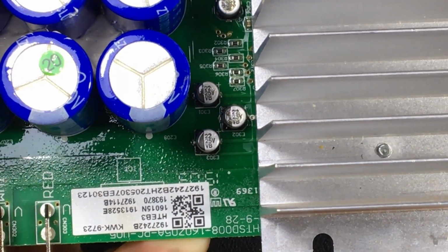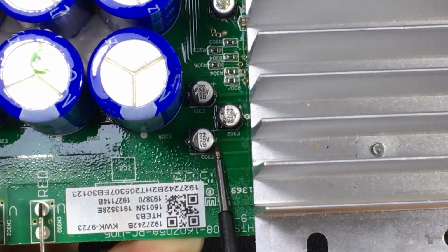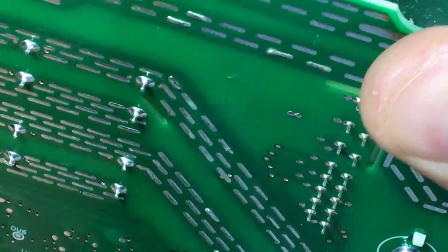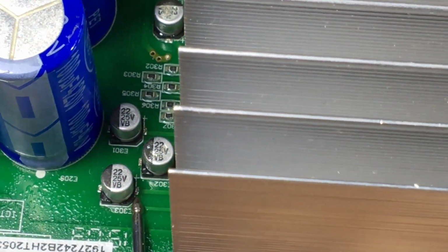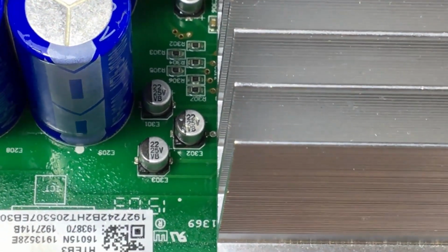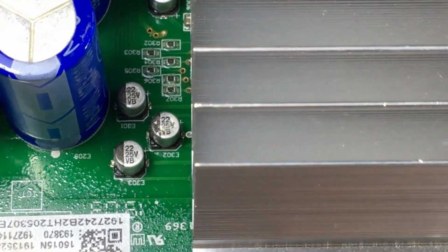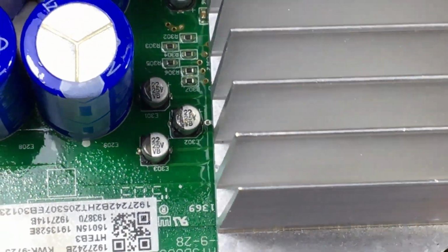Well, these capacitors are type SMD. This means that they are soldered on one side of the board, they do not pass through to the other side. So, to disassemble them, we have to heat with the soldering iron at this point and this one. And these capacitors come out. Later, in the soldering practice, we will be explaining how to use solder and a soldering iron. So, don't worry about that.